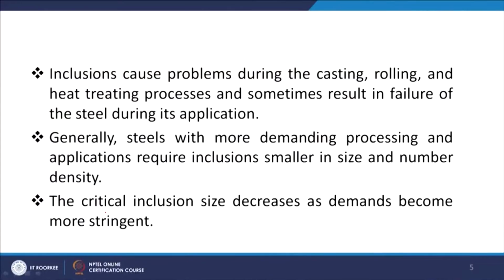So, that is why more demanding processing and applications are required nowadays, and the critical inclusion size decreases as demands become more and more stringent. So, you say that the inclusion size should be not more than this size whenever we talk about those very demanding steels, or wherever you have to use the steel for critical applications.